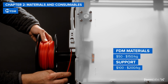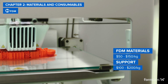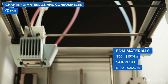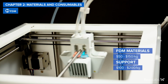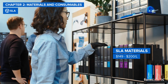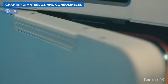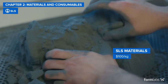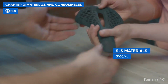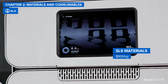On average, FDM materials usually cost the least, but a higher need for support structures and discrete support materials that are required for more complex parts can substantially increase material costs. SLA materials usually carry a slightly more premium price tag. SLS material costs are in between FDM and SLA, but because SLS 3D printing requires no support structures and unfused powder can be reused, material cost can be significantly lowered.